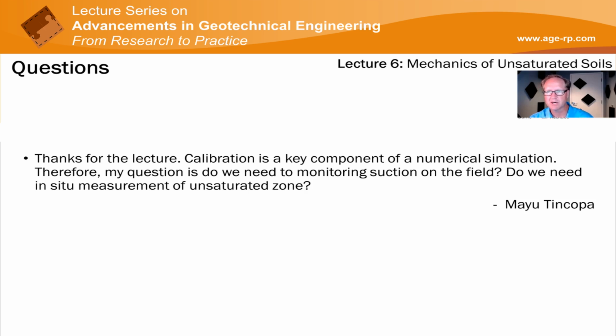Like, we put in piezometers and we measure groundwater fluctuations, but for example, there have been proven cases where the groundwater table is almost stable in a slope or in some kind of earth structure, and yet you get a big rainfall and it wipes out the soil suctions and you get a gigantic failure.